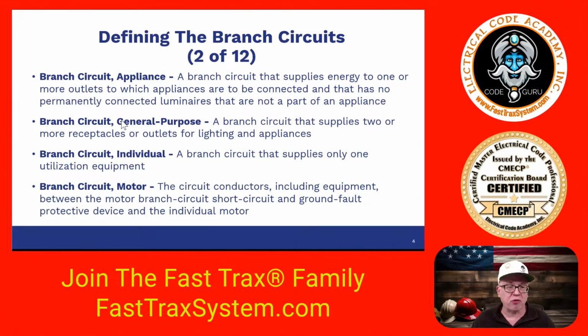Next, you have the general purpose. General purpose is picking up things like you're going to have just a receptacle that an engineer adds in a hallway, let's say. Or maybe in residential, we talk about general purpose. It may be the receptacles in your bedroom, living room, things like that. They're just general purpose applications. And they typically are on with not only the branch circuit for the lighting, but also they have the receptacles, so you can have both of those on the same general purpose branch circuit.